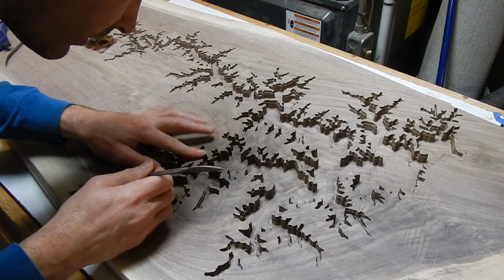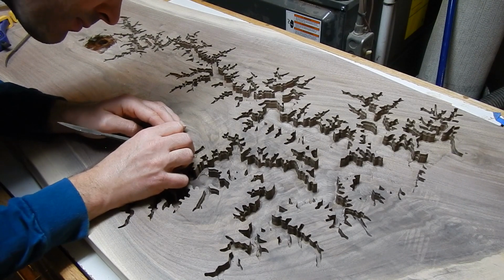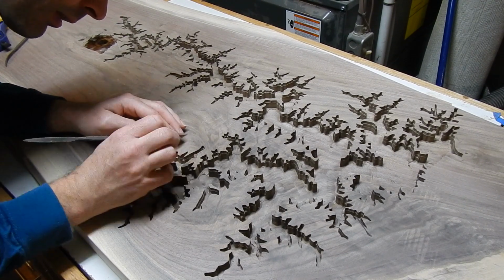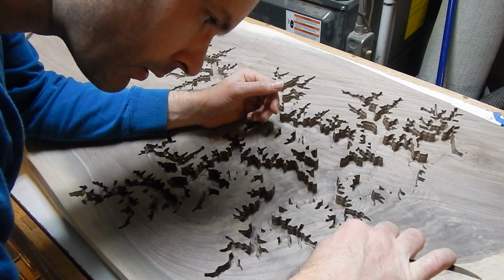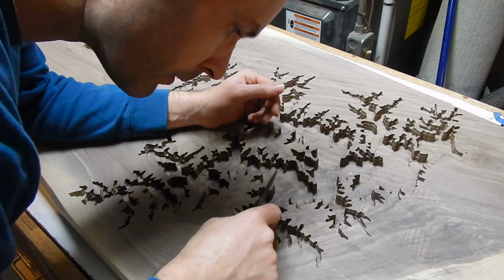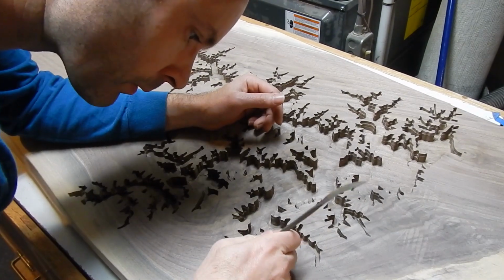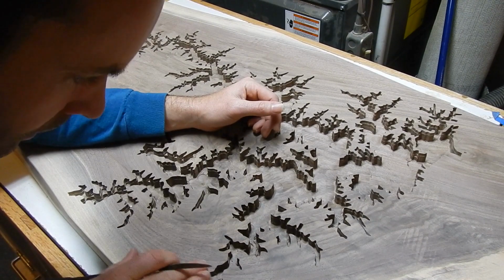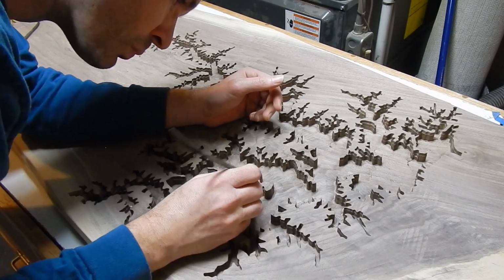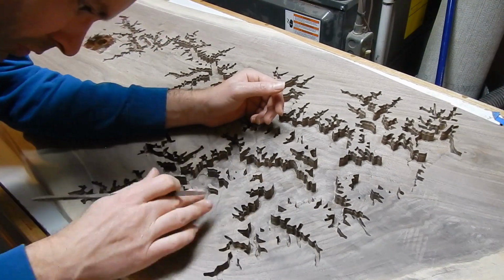The CNC machine left a burr on pretty much all of the edges. I used a rasp and some files to clean up the edges to leave a nice clean edge so that when we poured the epoxy and sanded it down, we wouldn't see any of the burrs. I also noticed there were a couple of cracks and knots that I wanted to fill so that they'd be clear or black as opposed to having a blue fill of the epoxy.